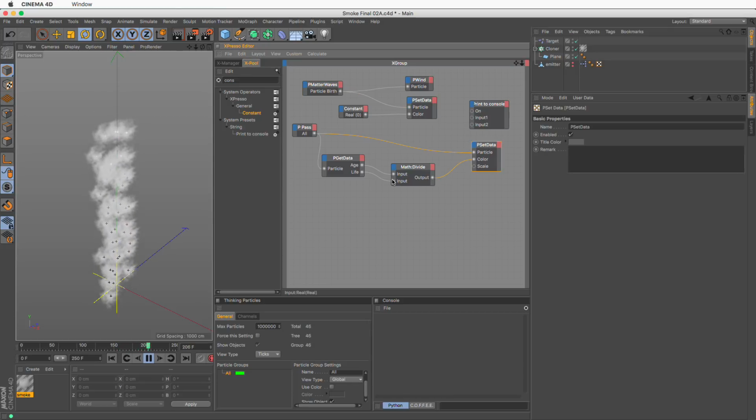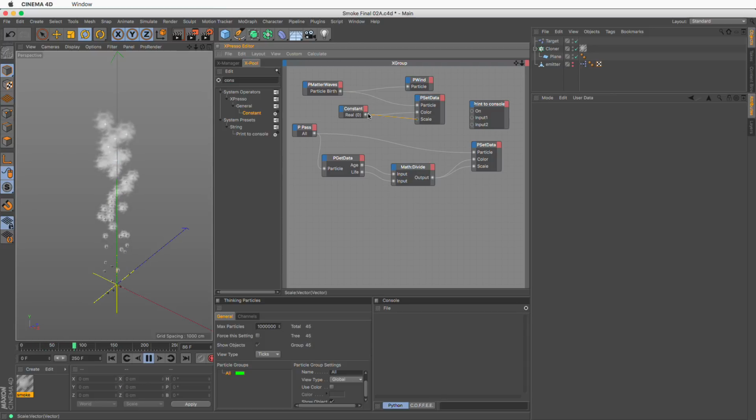Now this scale parameter needs to be sort of equivalent of our color. So what I'm going to do is put this in here, and you can see immediately that we get this wonderful flashing, and then these grow older. And the reason again is because when they are generated, they are at the default scale. So what do? Well, we add the scale parameter here. Command double click to expand this and connect it here, and now everything is fine.